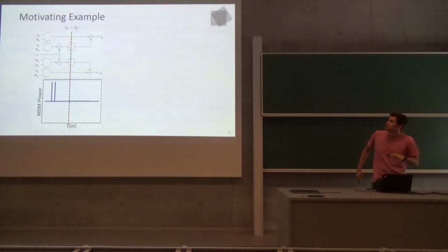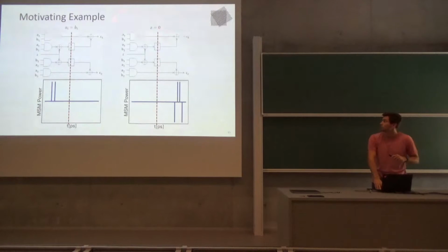But if you break one of these independence assumptions and run TVLA, no matter how simple the model, even one based on just a logical simulation, with delays constructed by a simple delta delay module saying each gate in the cell has the same delay, you will start seeing some leakage. If you take the same circuit and turn off the mask and do the same thing, you will see the leakage again.